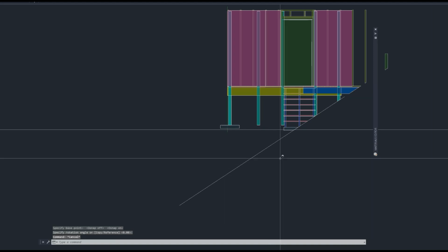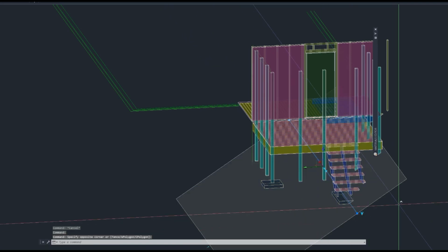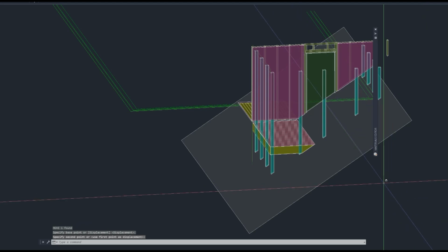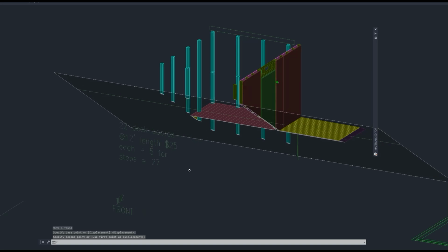Since only one slice plane can be in a drawing at a time, you will have to come up with clever methods to get multiple slice drawings on one plotting sheet, such as maybe cross-referencing from one drawing of the model, then slicing from that reference of each view required, then creating multiple plotting viewports, but I'm positive it can be done.